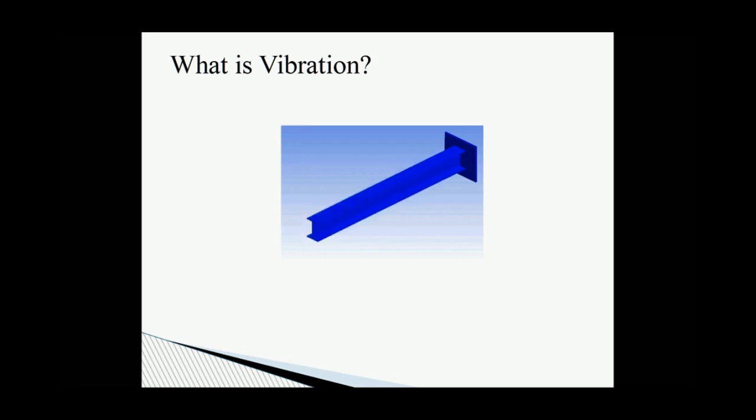You can look at the frequencies at which your modes occur, and at the frequencies and amplitudes of the vibration source, the force that's causing your vibration, which could be an engine or wind passing across a tower or building, and determine whether or not those modes are in the operating range of your system, and whether or not your structure will be damaged as a result of the operational vibrations that it will be exposed to.